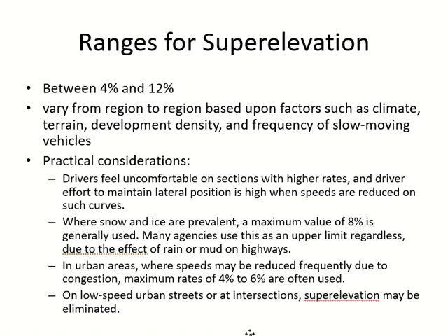Then we have slow moving vehicles. Which are the slow moving vehicles? Trucks. So for trucks, should I increase superelevation or decrease? Decrease. Again, because of the balance problem, slipping or loss of balance.